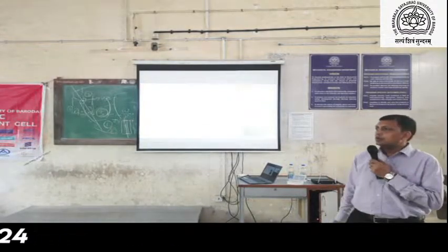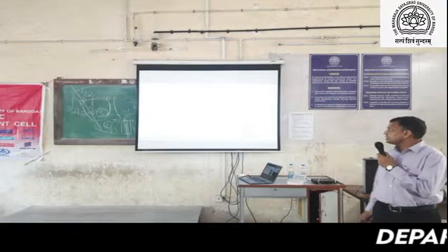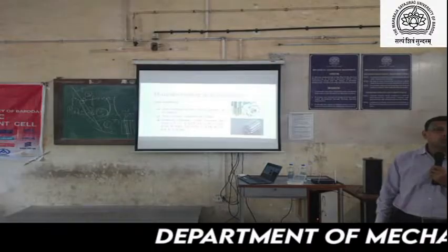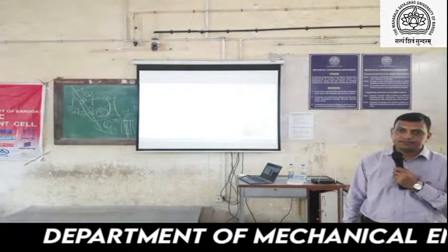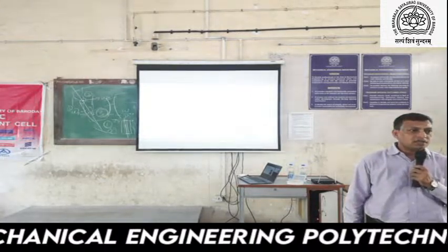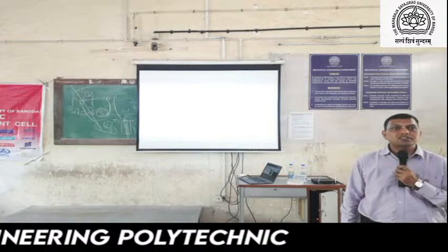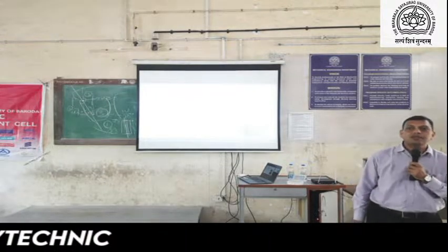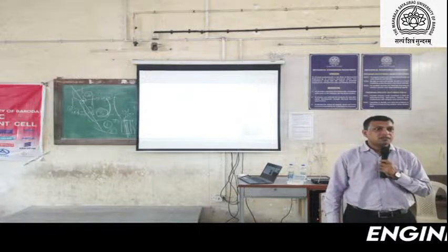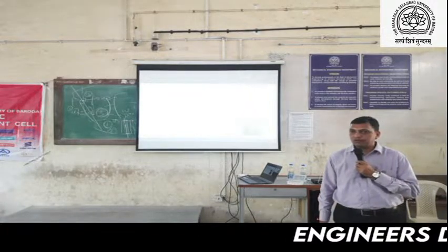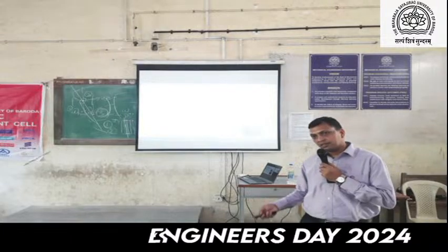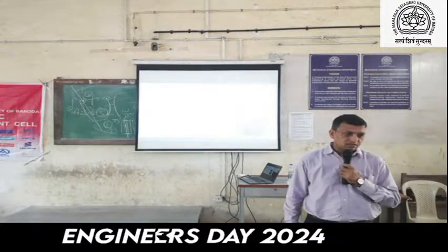After rough manufacturing, we go for the hobbing. Hobbing is nothing but the tooth cutting of the gear. In this case, we require a particular cutter based on the size. The size can be defined based on the model. Any gearbox has a specific size based on that model. Based on the model, we can specify the capacity of the gearbox.